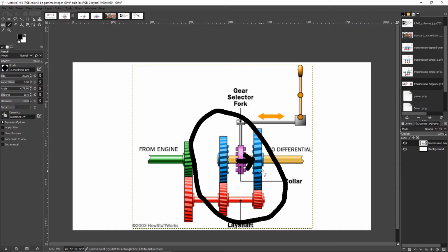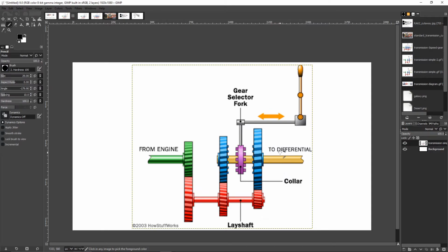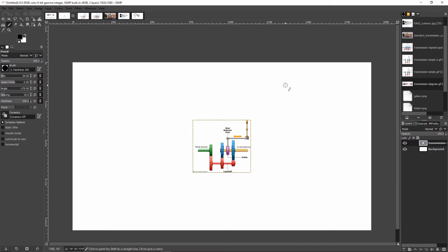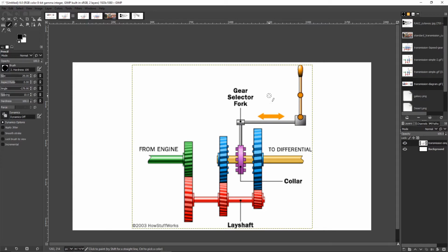And if you're shifting really fast, really hard, and your RPM and output are not the same, then that's going to tear those synchronizers up. Because we have these synchronizers, though, you don't necessarily need the clutch to shift. I spoke about that a little bit last week. So you absolutely could go from first to second without using the clutch, but when you do that, keep in mind that one thing I can control is engine RPM.